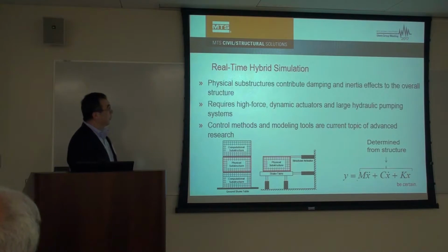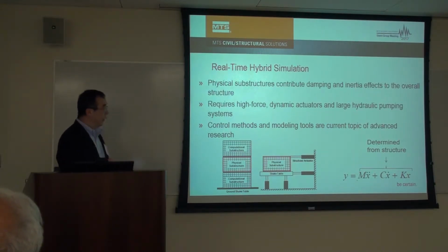We also have our real-time hybrid simulation solution, and in this case, the numerical and physical substructures provide all the inertial force, damping force, and stiffness force. For example, in this case, a shaker table wants to do a substructure test, maybe mid-level isolation.